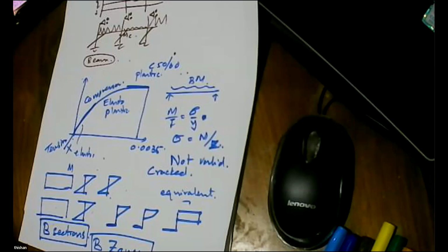Knowing that in Sri Lanka we have BG 24, 28, 30 big German machines that can easily break into rock, we decided to do something different: we are going to socket more. In our tender document, we had 6 meters socketing, 7 meters socketing, 5 meters socketing.